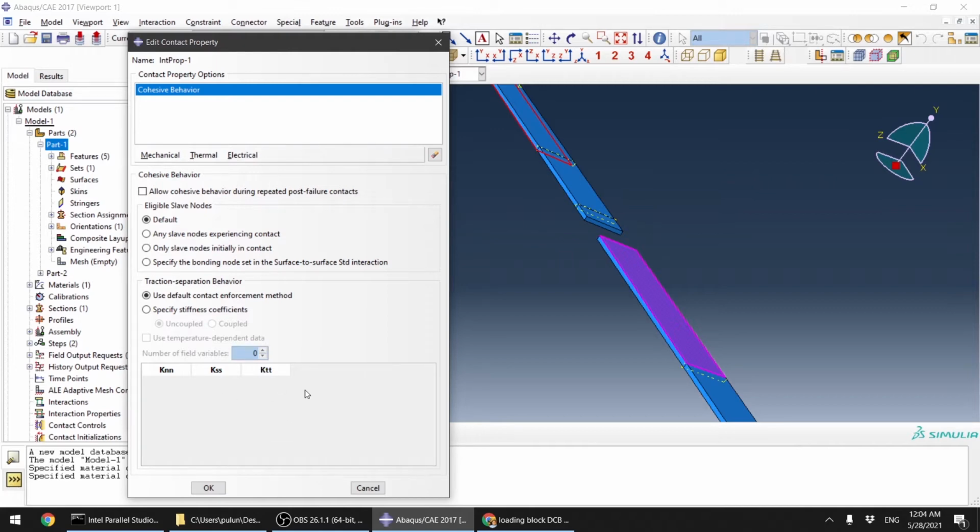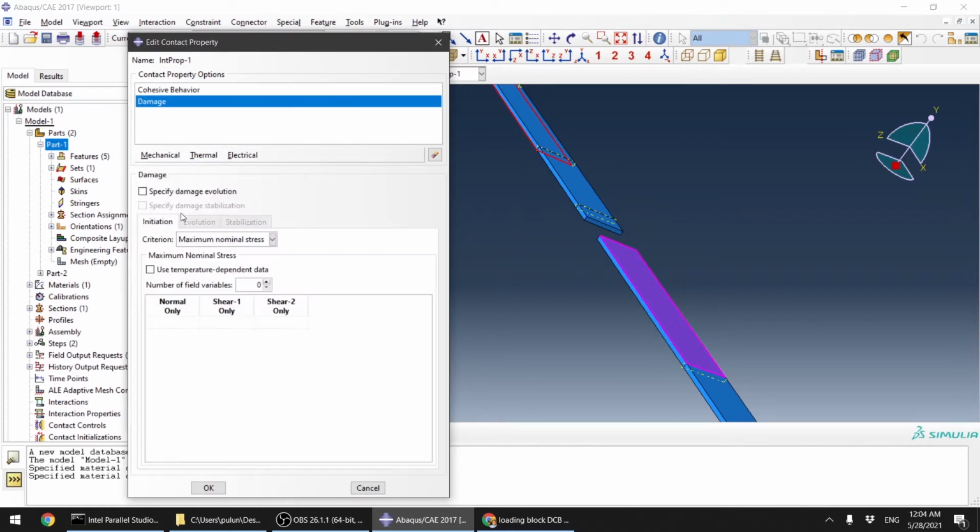When you're using cohesive elements, usually you need to put a big value. Here Abaqus can't estimate its own value, so just like that. And then for the damage, let's put 29 MPa. This is the typical value for epoxy, actually. So imagine now the glass PP has been glued with epoxy, and there's a criterion.